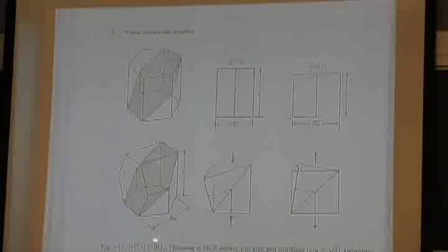If the crystal twins, and this is the twinning of the crystal, the crystal basically will have a plane. This is twinning on a pyramidal plane. And basically you start out with a hexagon here and then a hexagon here. It's just sort of rotated 180, rotated around. And it's called twinning. It occurs in copper alloys. It can occur in steels, not very often. But it's the primary deformation mechanism in materials like magnesium or titanium, alpha titanium.